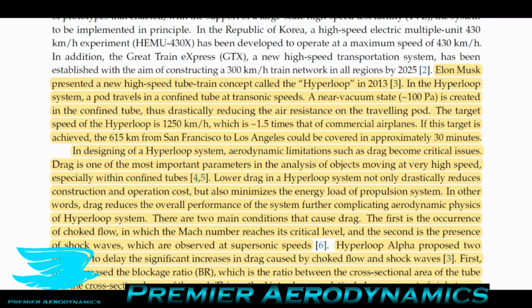So when they were at, let's say, a Mach number of 0.8, they found that the drag they were experiencing, the resistive force on the object they were traveling in, just started to increase, and they increased the speed more to Mach 0.9. It went up even more, and it just kept going up and up and up. And it seemed like it would get to a point where the drag would just be an infinite number, so you could never overcome that drag and break the sound barrier.